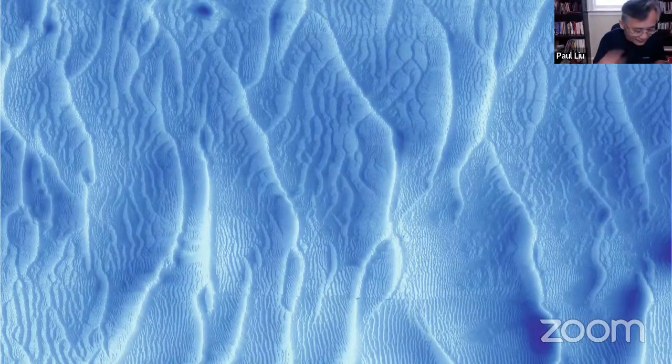Okay, I saw you did a series of along-channel surveys, mainly of the bedform and so on. Do you have any cross-channel periodic surveys, not only of the bedform, but also maybe a little bit of a sub-bottom profile? Then you can see how the bedding, how the stratigraphy changes over time.